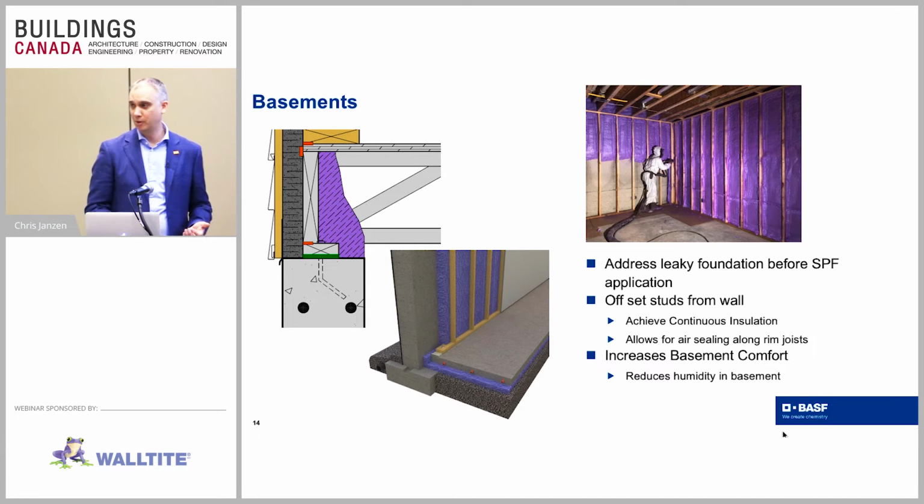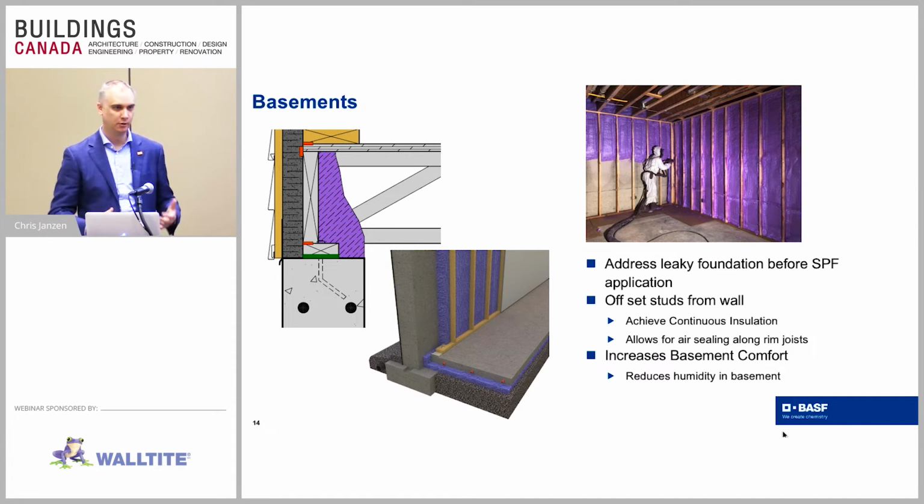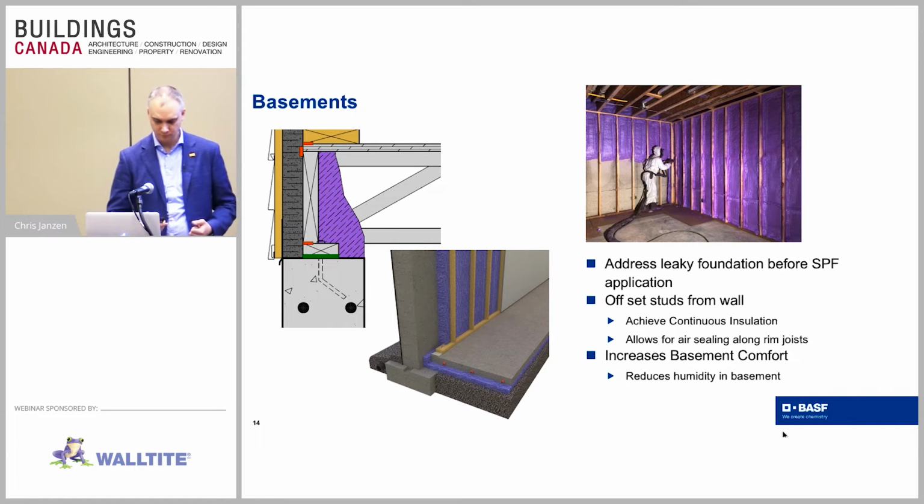One of the things when you're doing this is that spray foam needs to be covered by a thermal barrier. You can't leave the foam exposed to the occupants. It needs to be covered by drywall or some kind of cementitious thermal barrier to make sure that it meets the requirements of the building code. The building inspector won't issue final occupancy until the foam's all covered.